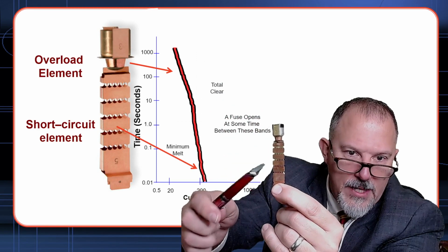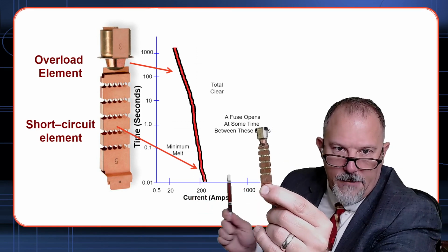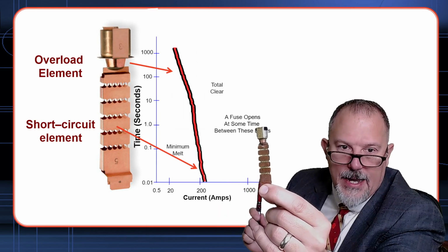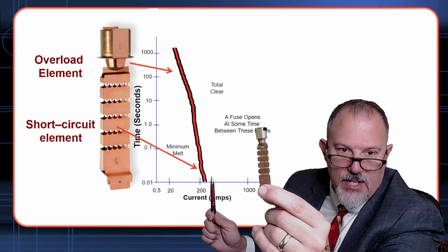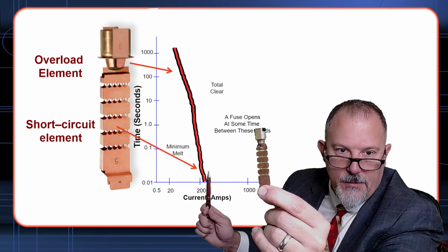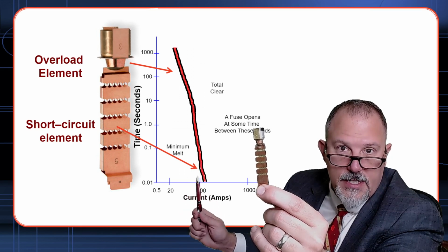These pinch points and that short circuit protection is down here, when the fault current is way higher, where it crosses 0.01 seconds, way up in this region. And arguably somewhere even along this portion of the TCC curve.